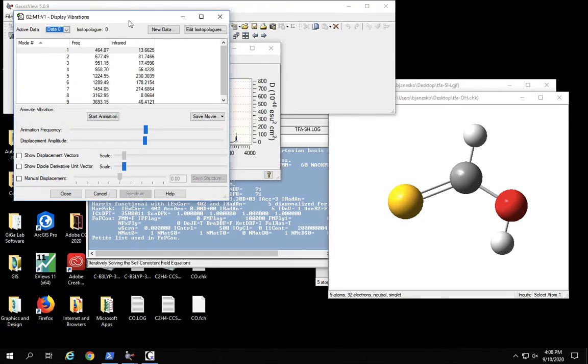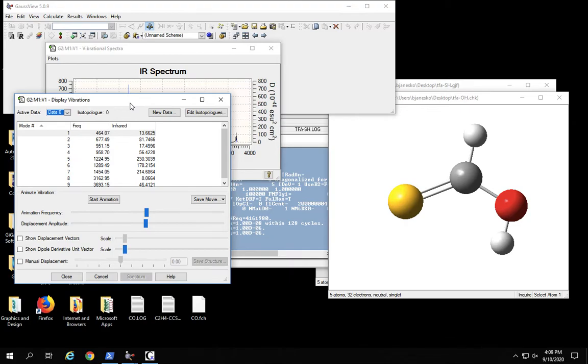And there's my results. Now I made one mistake, that I didn't have the Raman intensities computed. I think you need FREQ equals Raman to make that happen. Or you could do the optimization in one file and then take the optimized geometry and do FREQ equals Raman in the next file. So that's easy enough to do. But this is what I get.